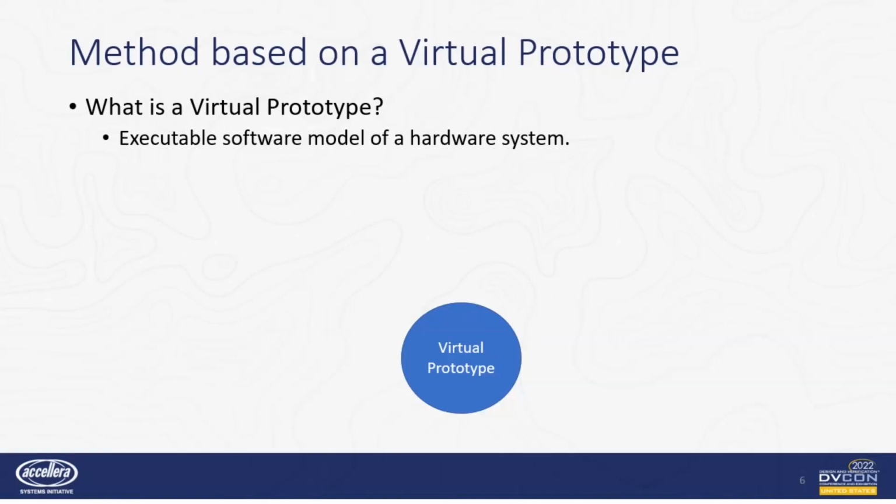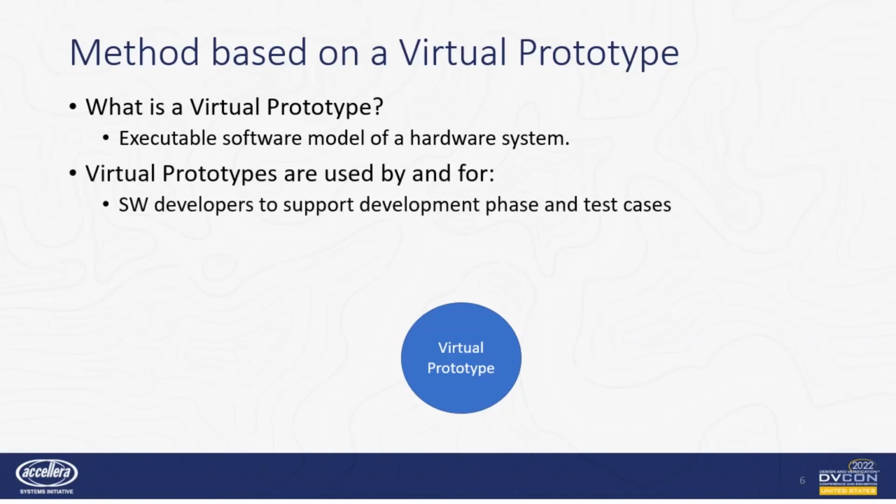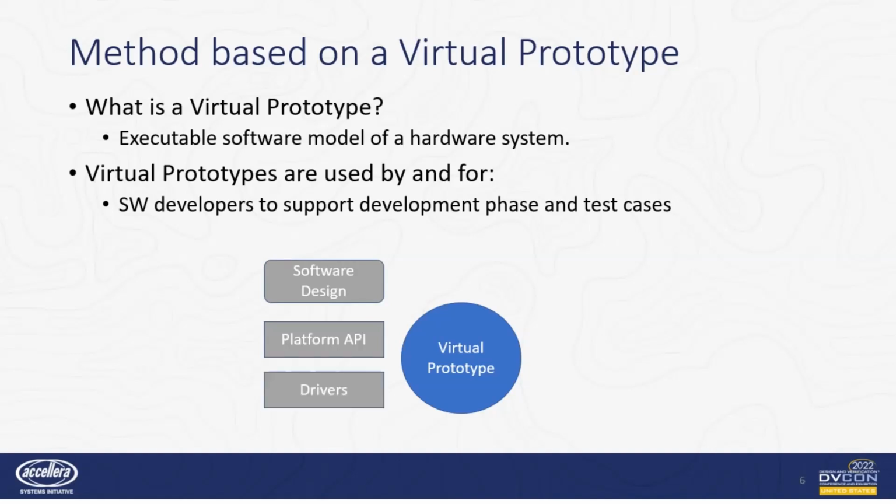Normally, virtual prototypes are models with reduced accuracy in comparison with RTL, usually written in C, C++, SystemC, or SystemC AMS. Virtual prototypes are used by and for software developers to support the development phase and test cases, to do the software design, to extend or elaborate the platform application interface, and to develop and detail drivers.